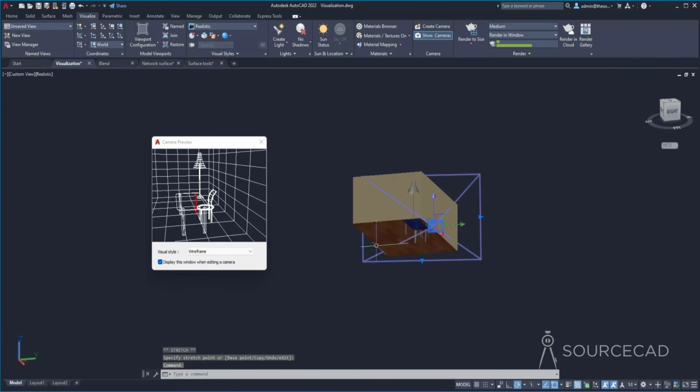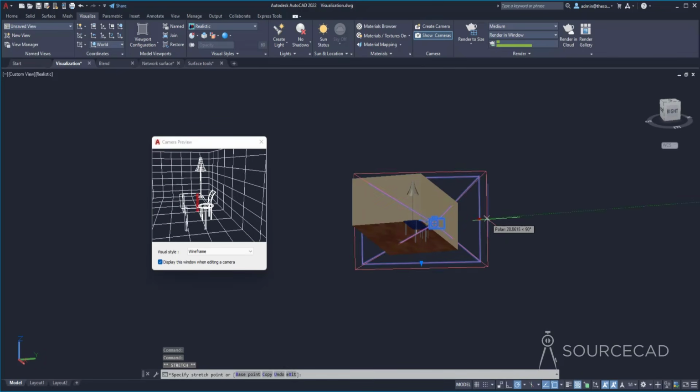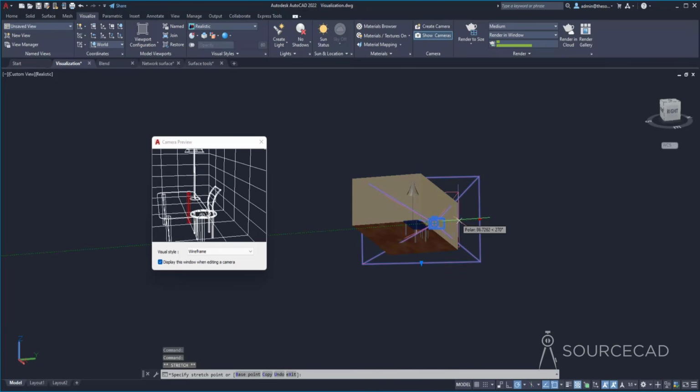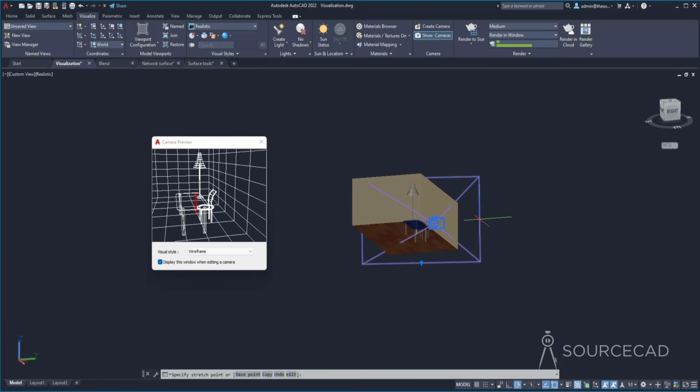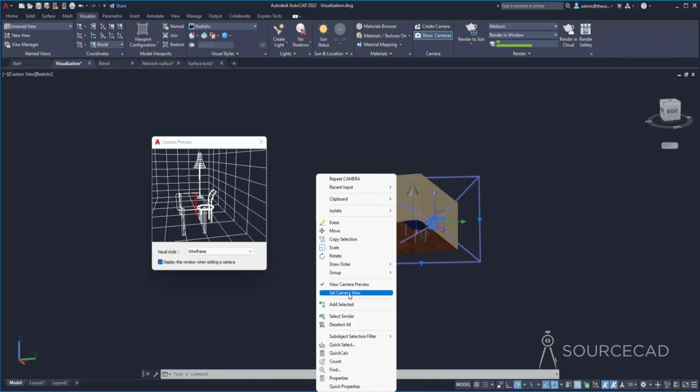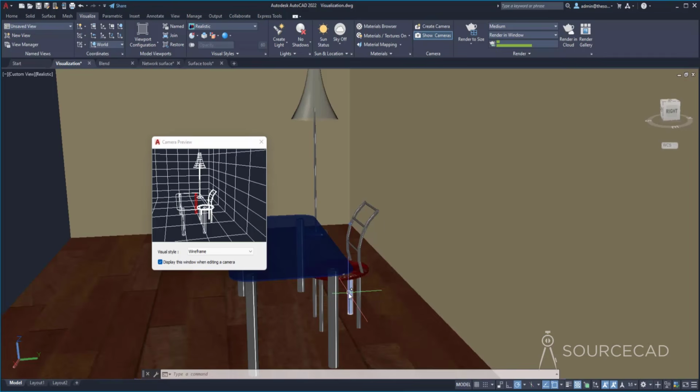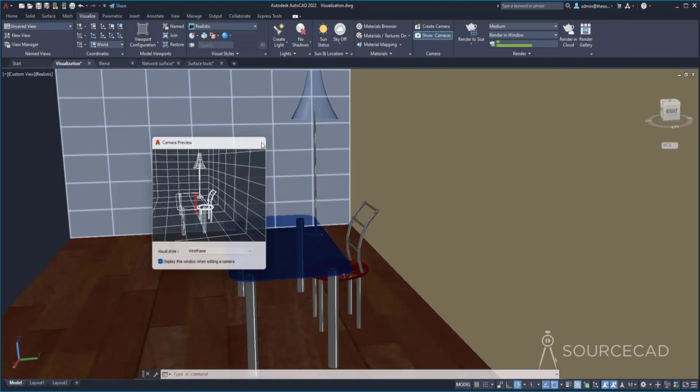And this is quite a good view if you want to keep it. And if you want to even change it, you can change the focal length simply by clicking here, and then you can change the area. So simply by changing the focal length, you can increase or decrease the amount of objects which fills into this area. So maybe I'll just leave the default value, and now I'll set this view as the default. And to do that, simply right click and select this set camera view. Now whatever the camera can see will be set as the default view. Close it, and there we are.